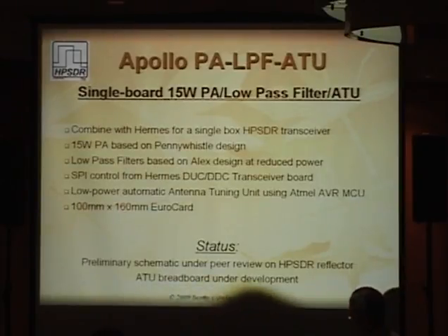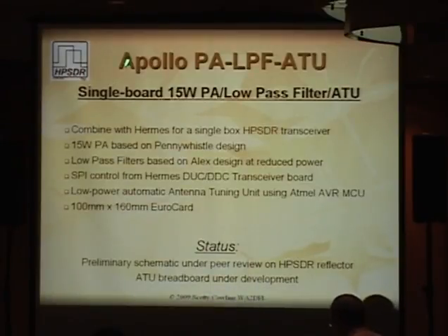This is basically the Apollo board. This is pretty amazing too because they're going to get all this on one board. They're going to put the 15-watt PA on here, the low-pass filters, and they're based on ALEX. They're not exactly the ALEX low-pass filters. And notice it's only low-pass filters and no high-pass filters on this board. SPI control, same as ALEX is. And the ATU, which is the intriguing part.